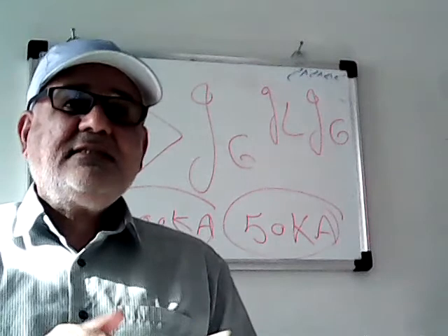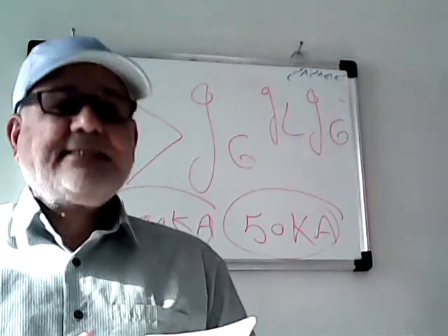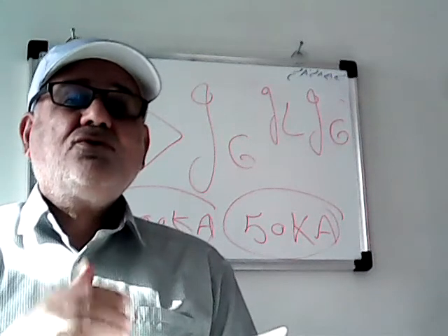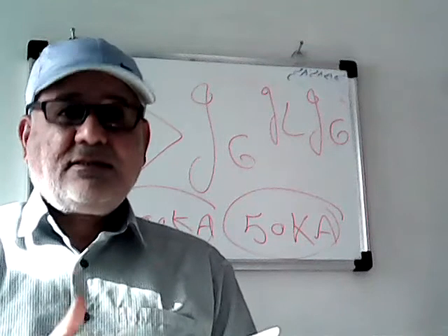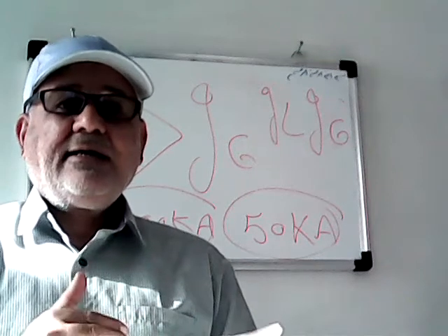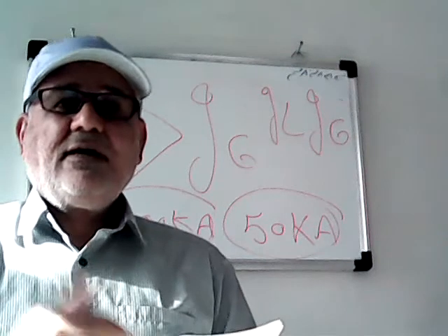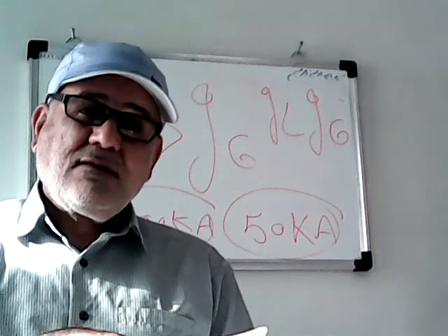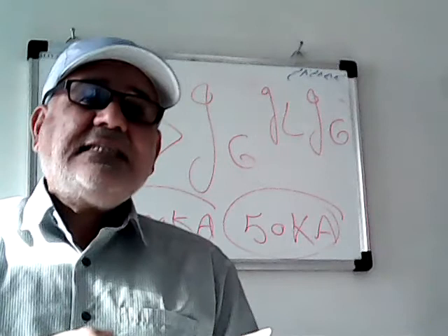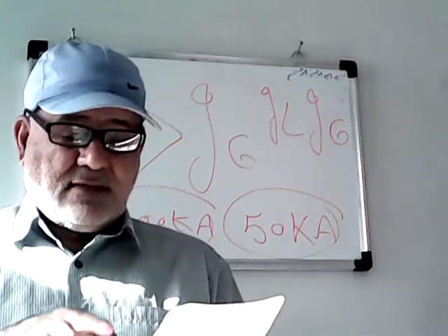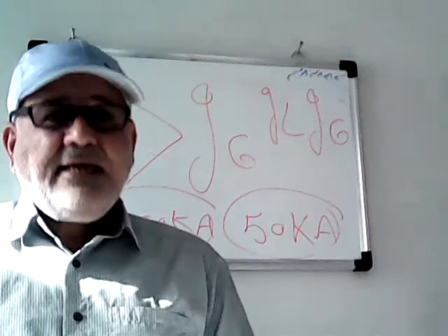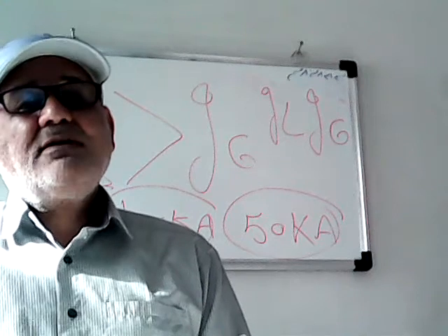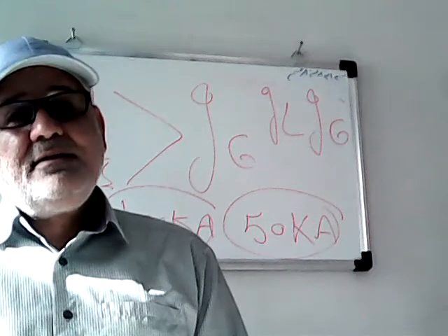The difference between switching AC1, AC3 and AC4 is that we have to choose different contactors, for example DILM, and also different auxiliary contacts for AC3, AC1 and AC4. Okay, here I just want to describe switching AC3 according to VDE and IEC.